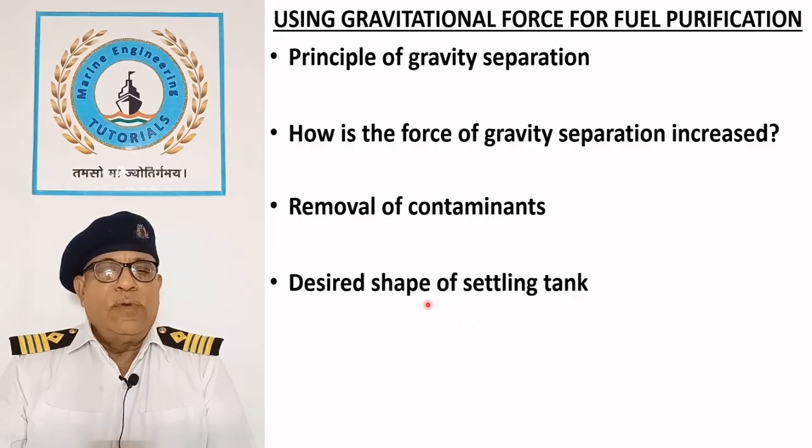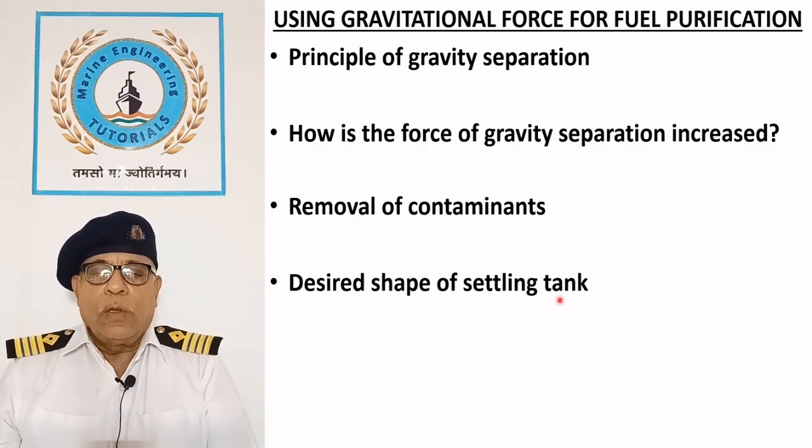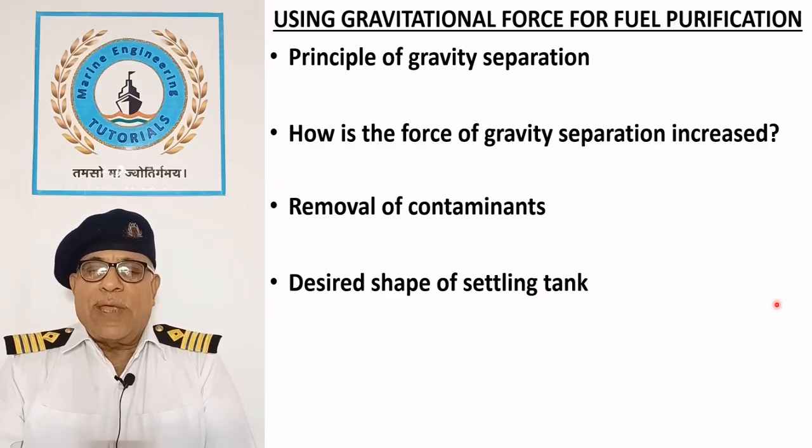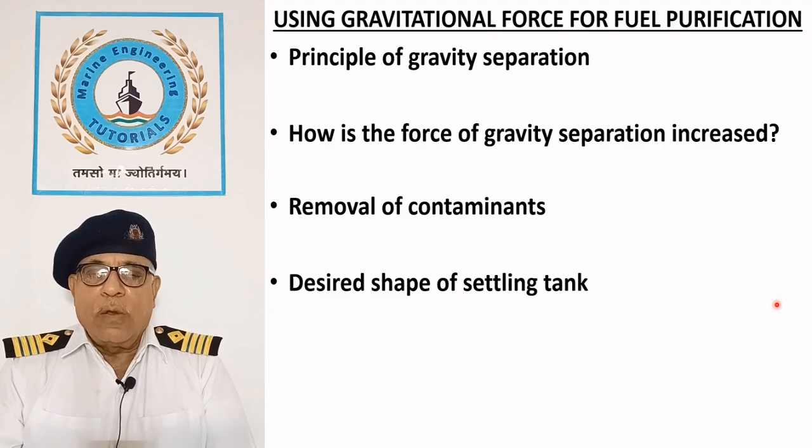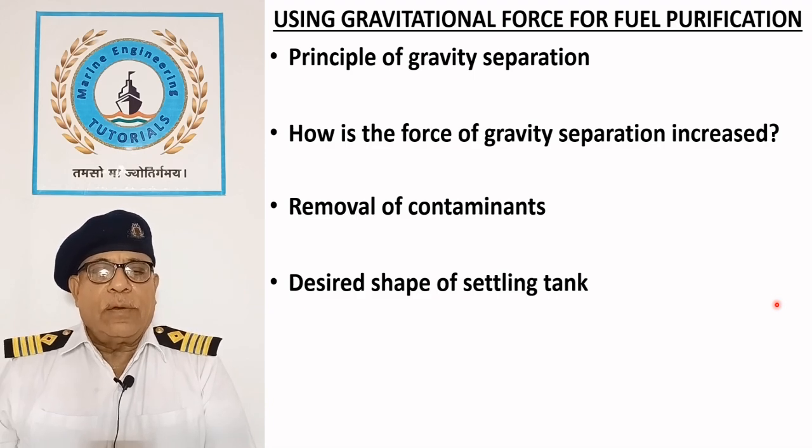Desired shape of settling tank. The settling tank has a narrow and deep construction so that a large gravity head is available for separation, and the ship's rolling and pitching movements do not mix the separated water with oil again.